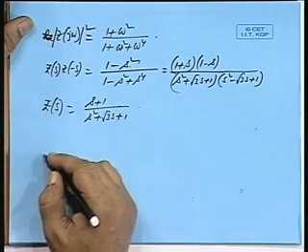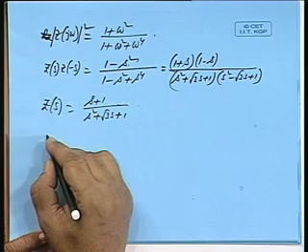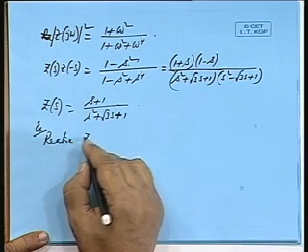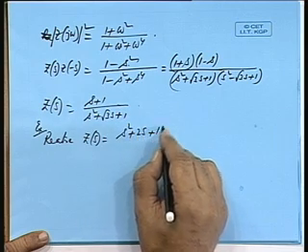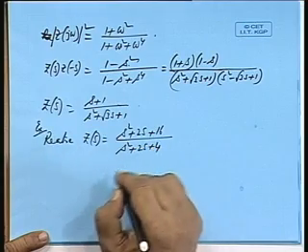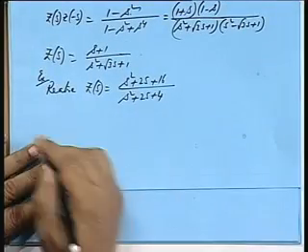Okay, now I will take general RLC synthesis by both Brune's method and Bott-Duffin's method. This is just revising what we have learnt earlier. So realize Zs equal to (s squared plus 2s plus 16) divided by (s squared plus 2s plus 4). Okay. Let us try by Brune's synthesis.